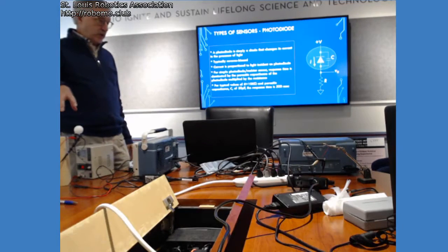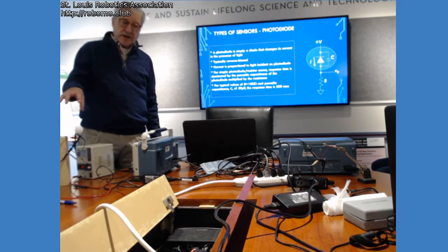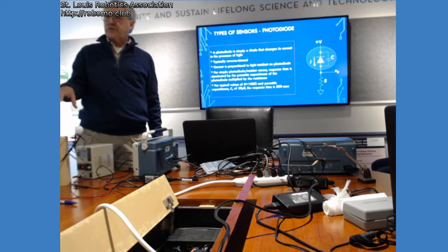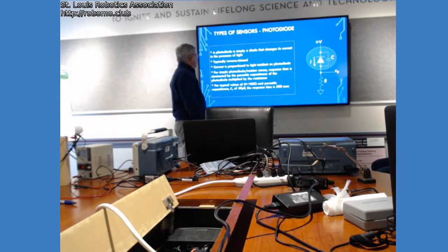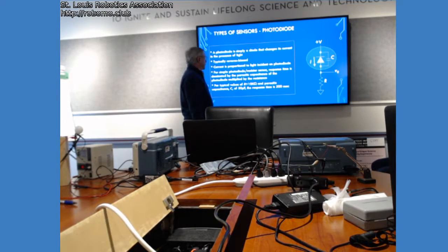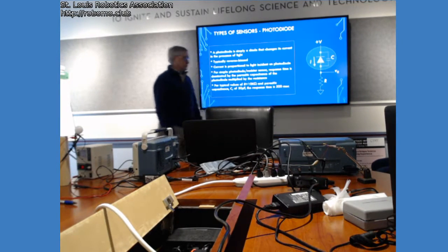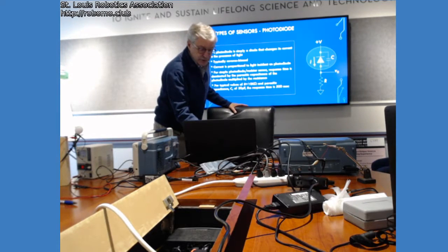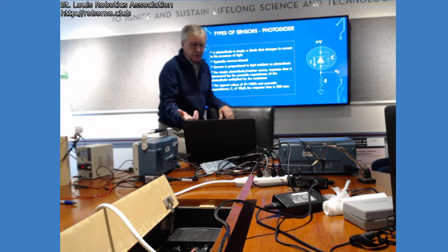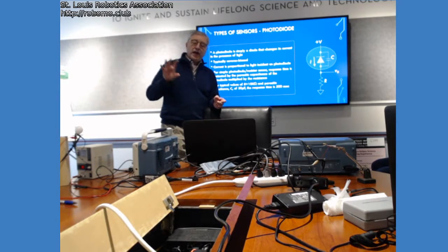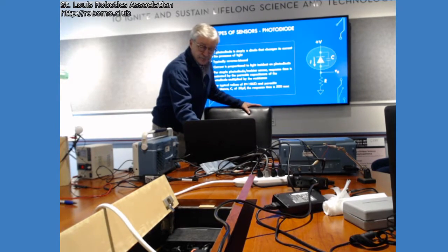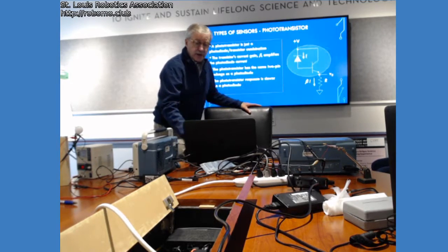And as you'll see here in a minute, I'll be lucky if I can get it up to 20 kilohertz, a 50 microsecond period. So the response for most of these photodiode applications is going to be determined by the parallel combination of that resistor and the capacitance of the photodiode.